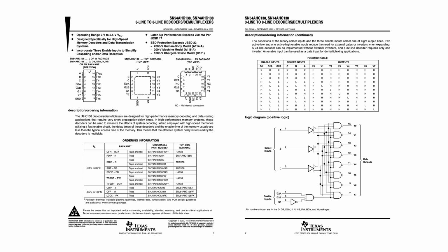So let's go back to the ever so handy 74138 3-to-8 decoder. Just as a reminder, this chip takes a 3-bit binary number as an input and asserts a single corresponding active low output. We can use one of these to generate the read and the write strobes. Let's take a look in Logisim to see how this can be done.